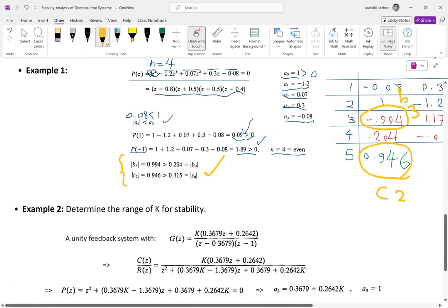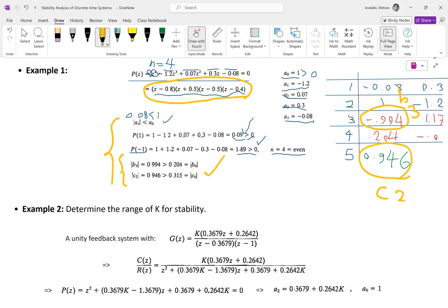If that's the case, since all five conditions are satisfied, the system is stable and it has basically all roots inside the unit circle. And clearly, if you ever ran the command roots on this, you can see that, of course, they are. They're all within the unit circle.